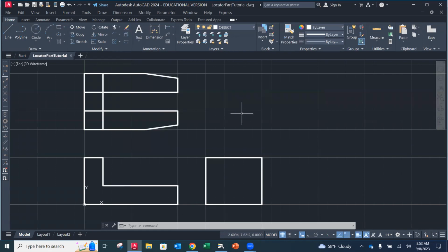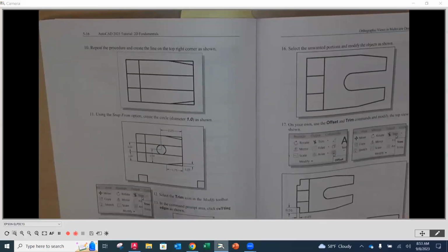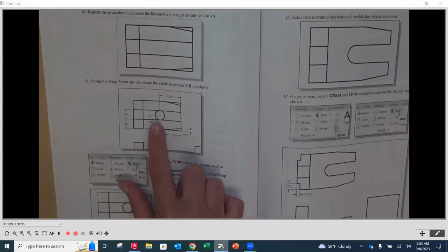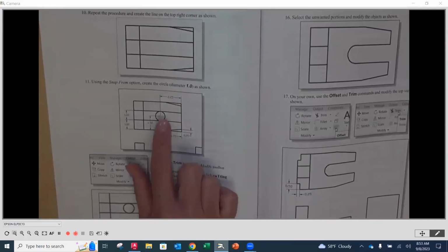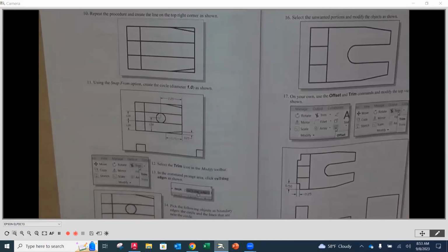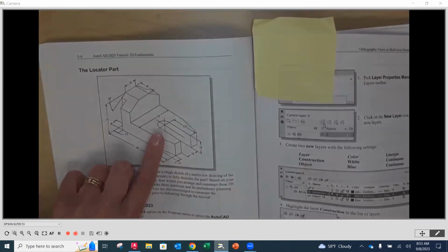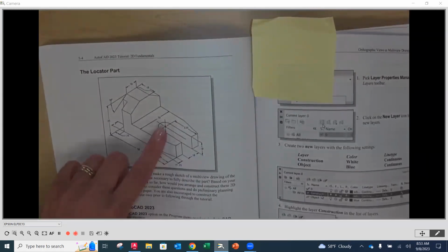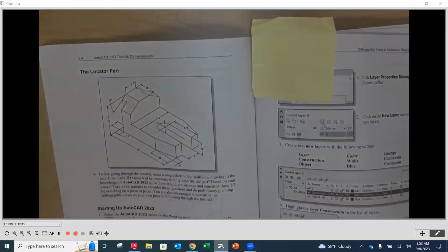Okay, good. So if we go to page 516 in our book, we've kind of got these parts. We went ahead and did a little bit more trimming right away. We're going to place this circle right there to create that round, okay? And notice that they're giving us the coordinates. But again, those coordinates come from the original drawing here. So they're 2 1/4 in from that right edge, and it's centered on the actual part, so 1 1/2 up, okay?